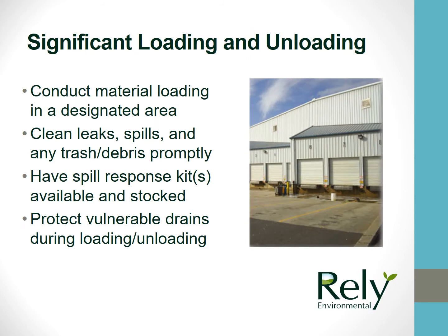Loading and unloading can also contribute to stormwater pollution. Conduct material loading in a designated area. Clean any leaks, spills, and any trash debris promptly. Have a spill response kit available and stocked, and protect any vulnerable drains during loading and unloading.